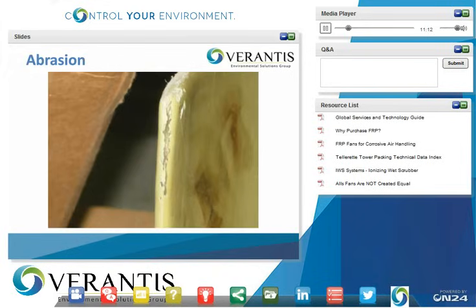This photo shows abrasion. It could be particulate in the system, or it could be moisture causing the abrasion along the leading edge of the blade. The gel coat's coming off and exposing the glass fibers. Once they're exposed, now you're subject to chemical attack as well.